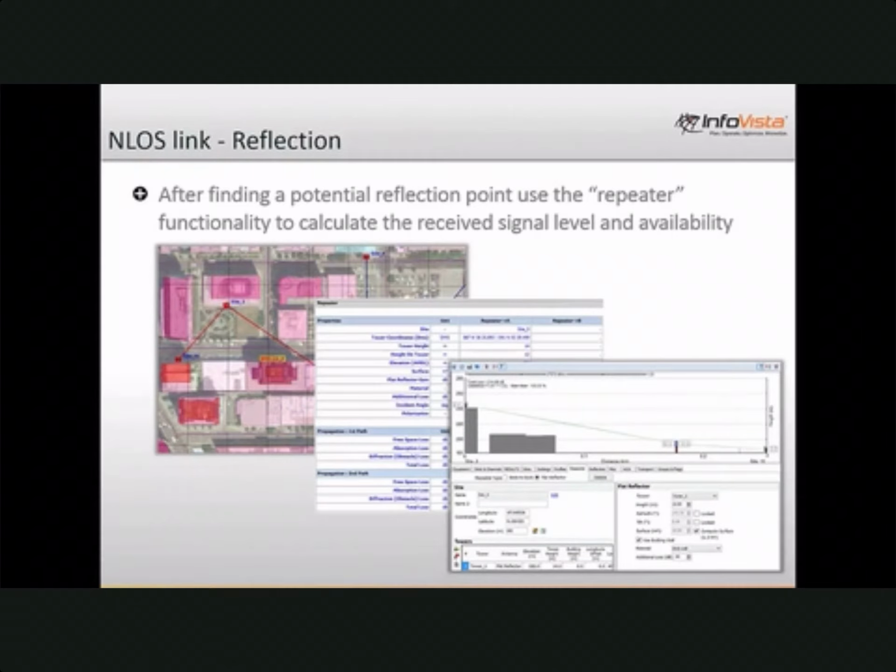In addition you can add some safety margin, an extra 5 dB or something, so 5-10 dB if you have glass and up to 20-25 if you have brick, and wood is in between. So something like that, and that will be included as a loss in your link budget, so the received signal level will be affected, the fade margin will be smaller, so availability will go down.